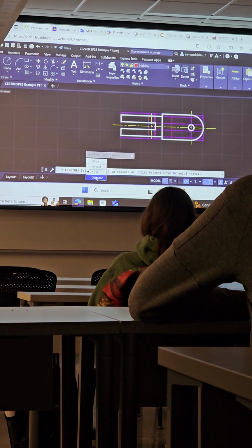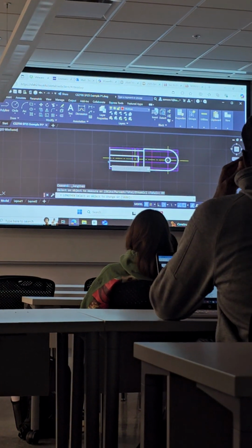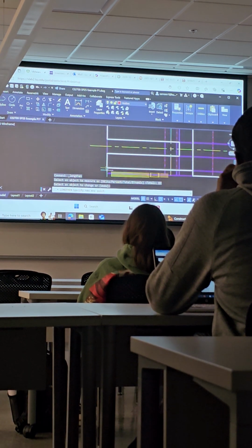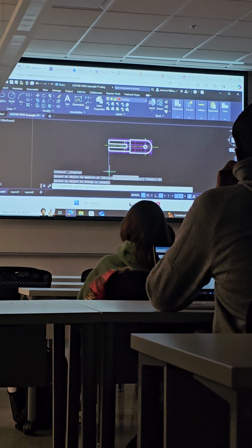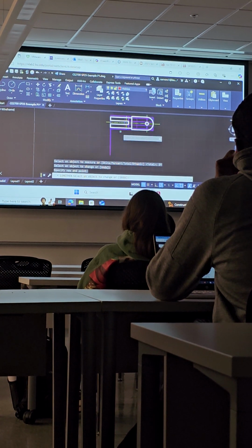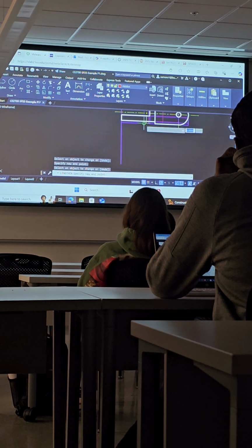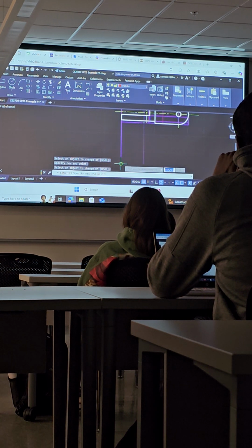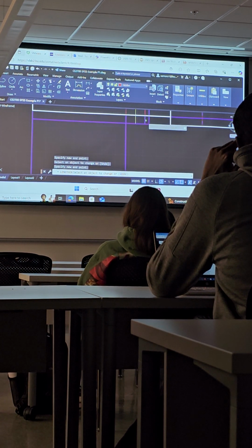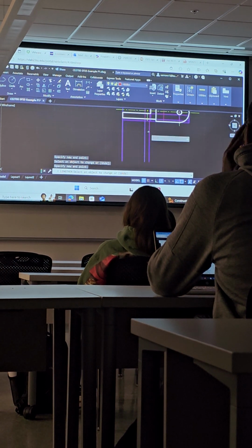That allows me to grab onto a line that's on the screen and just stretch it down. So if I zoom into this edge over here, for example, I can just grab onto that line and extend it down a bit. And I'll do the same thing for all of the vertical lines that I have as construction lines.